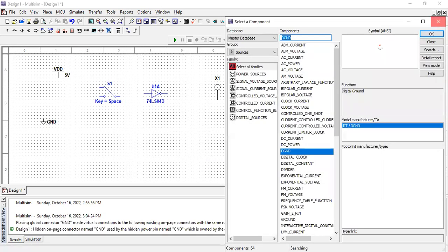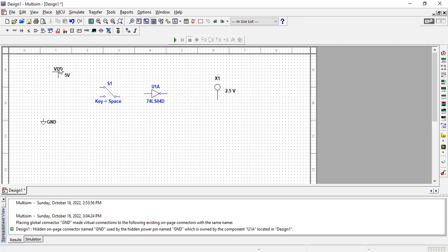Okay, so I need to explain over here the voltage source, VDD, and ground. When we are going to design any particular logic gate, we must have logic 1 or logic 0. In digital logic design systems, we normally represent 5 volts as the high logic 1 state and the ground as the 0 logic state. So whenever you are going to design any particular logical circuit, we must have these sources like VCC or VDD, and 5 volts is basically a level that is used to represent the high state 1, and the ground is basically a level that is used over here to represent the 0 state.